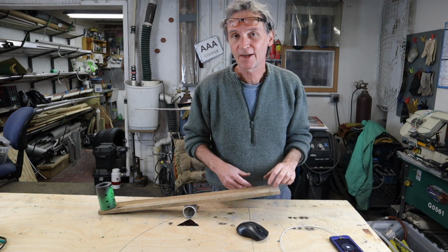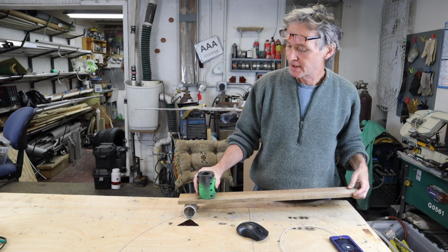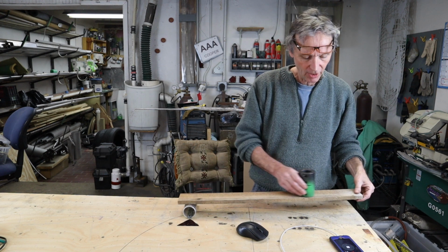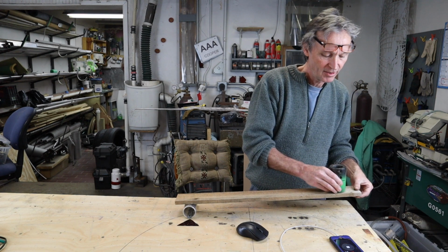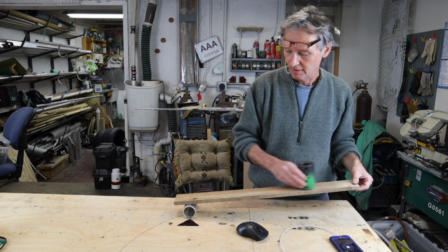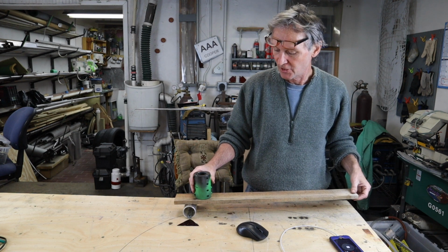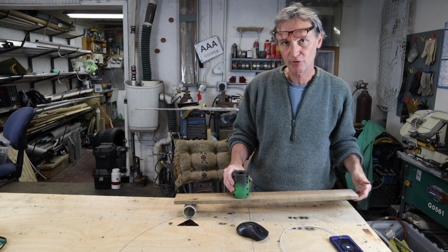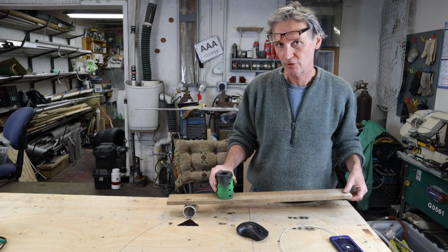Now we're back to second class seats on the train, in which the load is now on the same side of the fulcrum as the force is. And we can move the load backwards and forwards, but we can never move it past our force. So my hand is always moving more than the load is. And we can obviously make it easier for ourselves, but we get less movement down here. The other thing to note here is that the force and the load always move in the same direction, as opposed to the first class lever where they move in opposite directions. Now they're moving in the same direction.